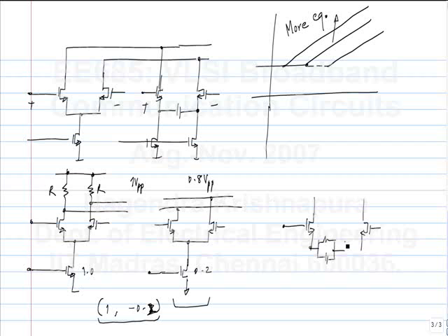Okay. So once you connect these resistors, what happens to the output amplitude? Will it reduce or increase? So let's say I use the same differential pair here and here, okay, and the same current. I mean the total current in these two is 1. Okay. So once you add this degeneration, the output amplitude will reduce, and then you can add some capacitance to get high frequency boost. So at a very crude level, they are more or less the same.